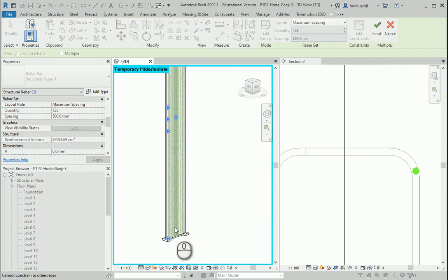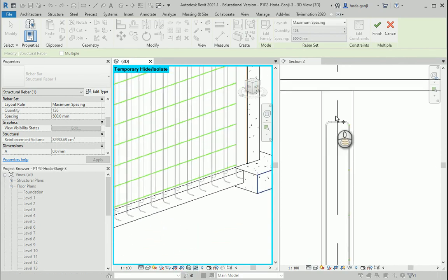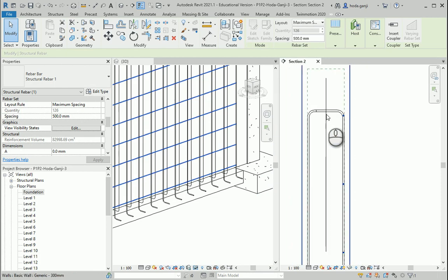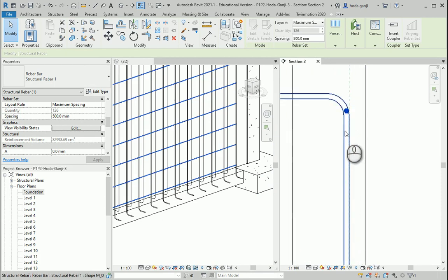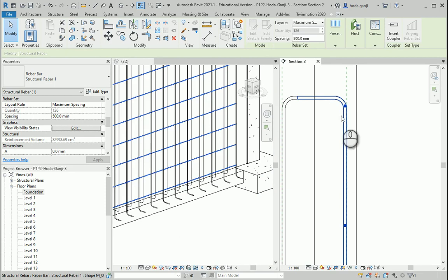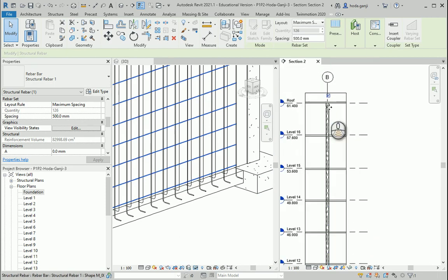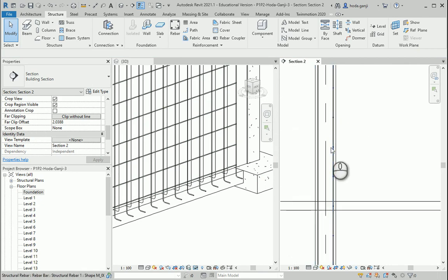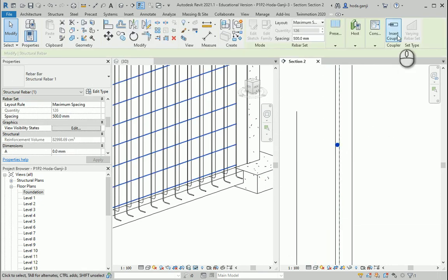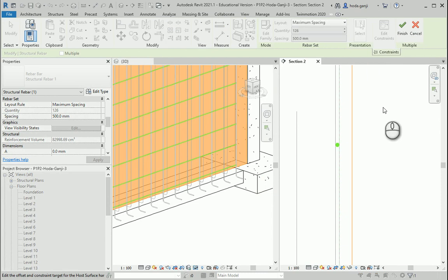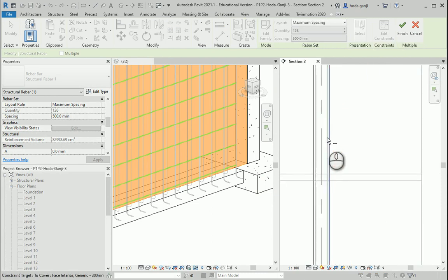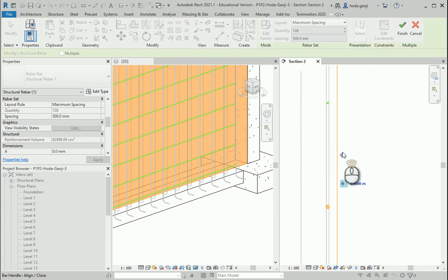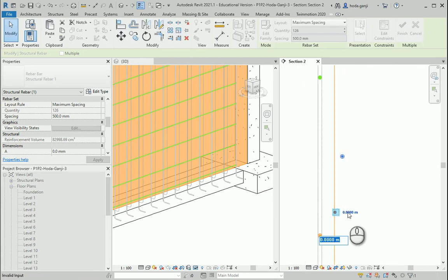At the bottom, here on this other view, actually, I want to move them a little bit inside, so it's not gonna have any overlaps with the other set of rebars. So for that, we need to go to this view, select them, go to edit constraints from here, and at the middle of it, there is one constraint here which allows you to move this inside.